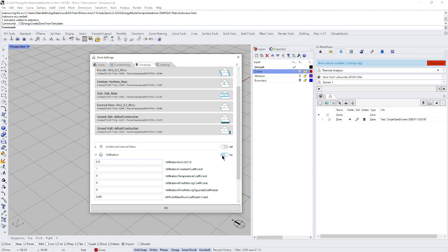And we can either turn this on or off. If you turn it off, you're going to have zero infiltration, which is crazy, impossible to do. So anyway, the preset's 0.5, which is very low, at least in U.S. construction. In the building in Manhattan that we're in, I bet that building has an ACH of 10 at 50 pascals, probably 10.0 or 12 maybe, might be a little less. I doubt it. Definitely the building in Old Westbury is something similar, I would imagine. So they're very leaky buildings.